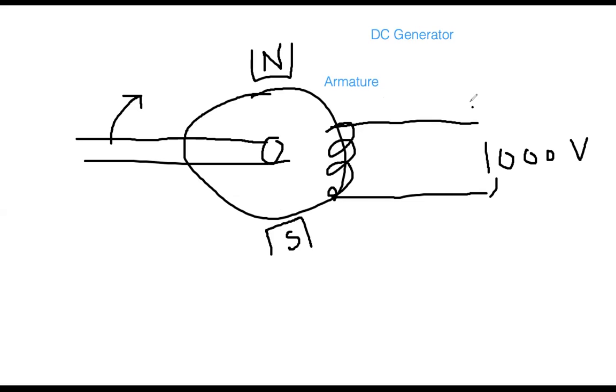Keep that in mind. Once the shaft rotates with the help of the prime mover, the voltage will build up here. And that is the DC voltage. But actually, what happens initially is not DC voltage. Initially, AC voltage is produced. The reason is that the coils are moving, but the magnetic field is fixed. This is the north pole, this is the south pole. So therefore, you see